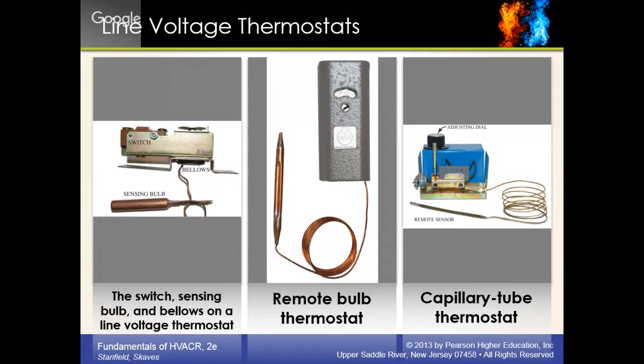This is what the inside of the pressure switch looks like, fellas. As the pressure rises from here, you can move this around, up and down, and then you take the diaphragm out. Right there. So as the pressure increases, it's going to move this toward the switch in here, and once it gets high enough, a switch gets made inside of there. Once the pressure gets high enough, it'll turn that off. This is what it looks like. You can hang on to the spring.